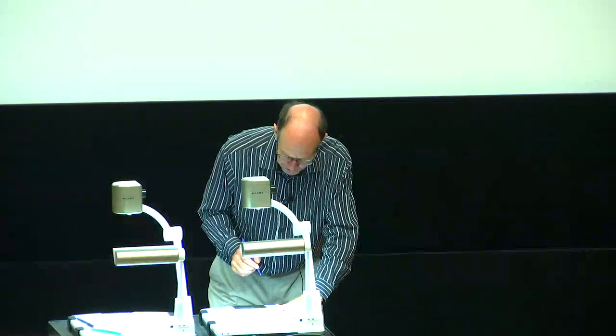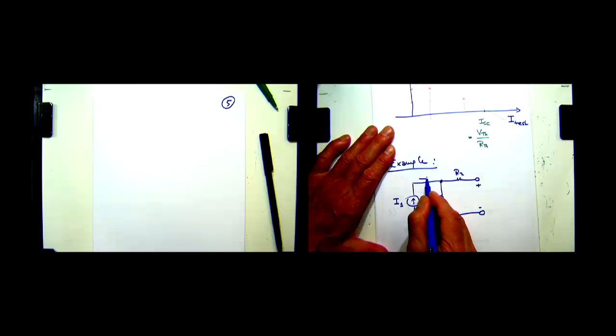Well, if this is open circuited, this current I1 here, of course, is going to flow out of the current source, right? Where is it going to go when it finds these two resistors? Is it going to flow into R1, or is it going to flow into R2? Into R1. Why? Well, because if it flows into R1, it hits a dead end over there where the plus sign is. There is nothing connected there because it's an open circuit. It cannot go any further. So it doesn't like that. It needs to flow the other direction.